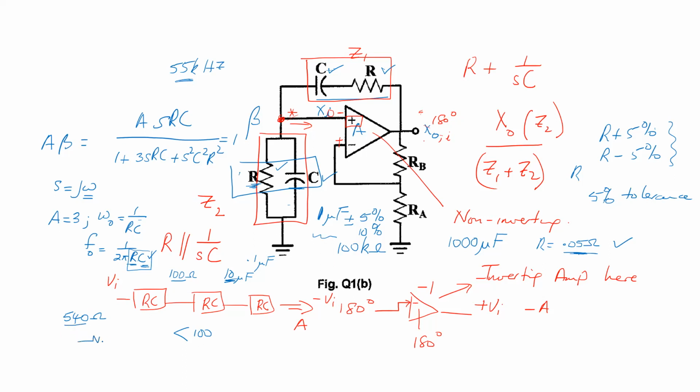Remember, with series and parallel combinations of resistors, you can make nearly any value that you want. So it's fairly easy to create an odd value in a practical application. It's a lot easier to create an odd value of resistance than it is to create an odd value of capacitance.